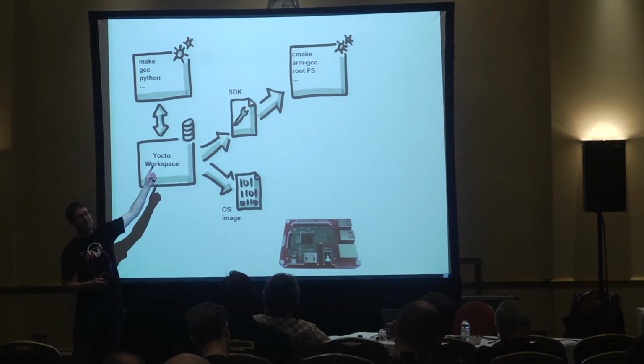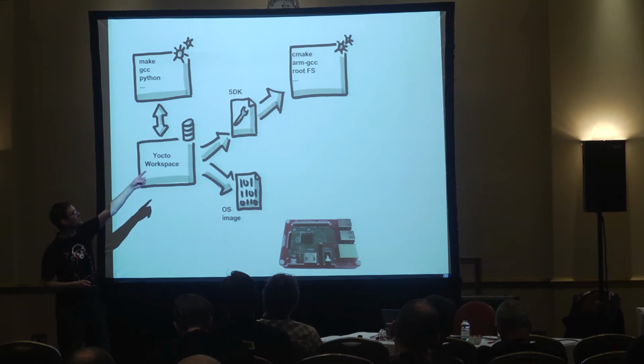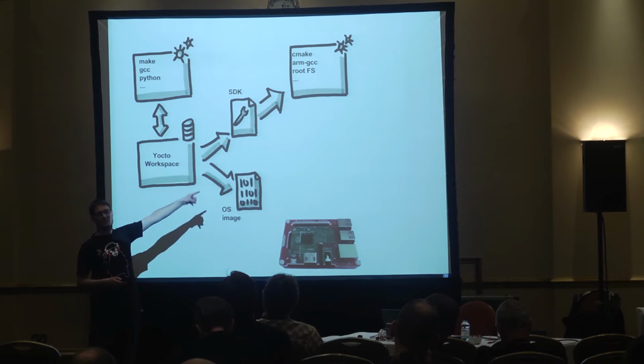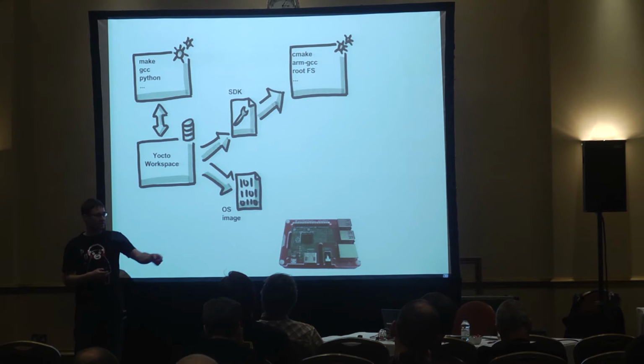And this SDK I install into another container, or create a new container out of it. Then I have a new container which contains the SDK installed. So I have a container with which I can generate binaries for the Raspberry Pi.